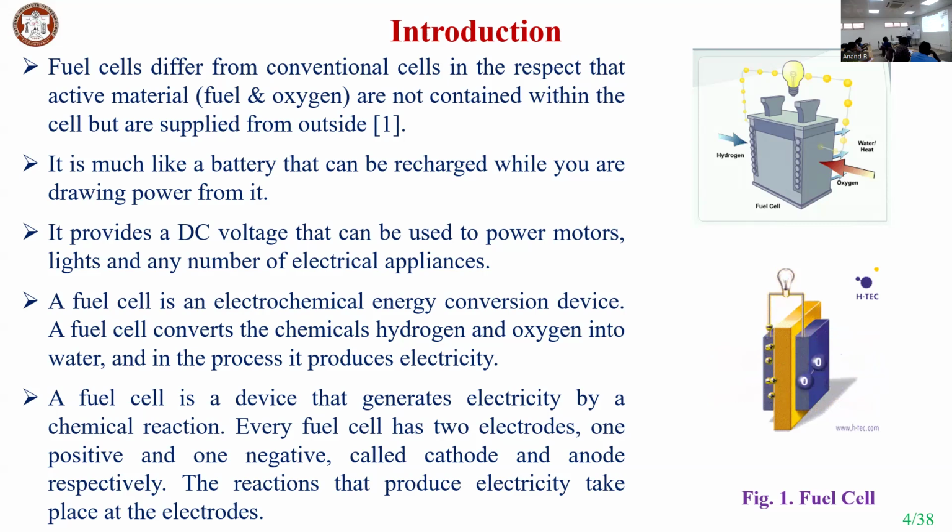Then this is a positive sign, I can say. But in case of water, you need to have a proper design of the anode surface, cathode surface, and then the GDL, gas diffusion layer. The design of all the components associated with the fuel cell also plays a major role in producing maximum electricity.